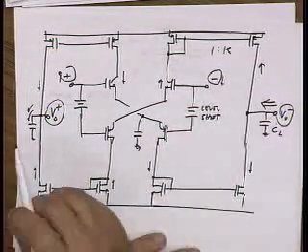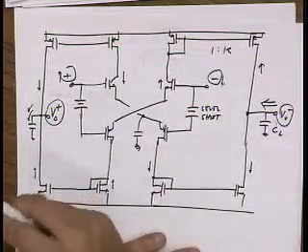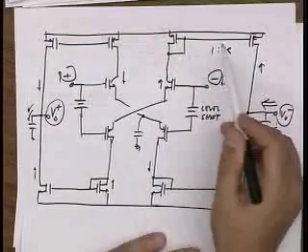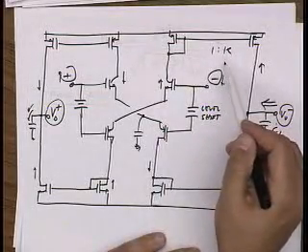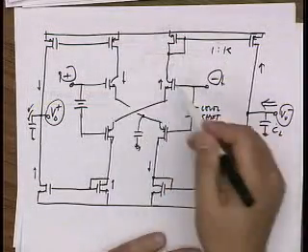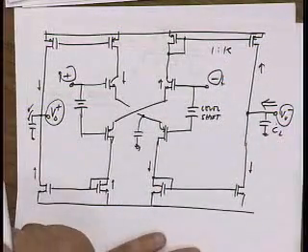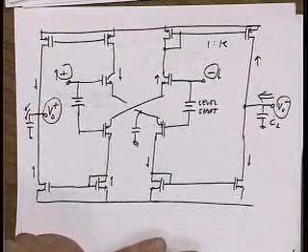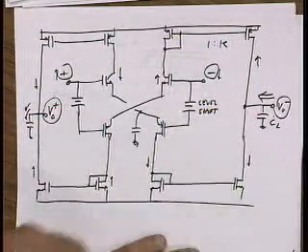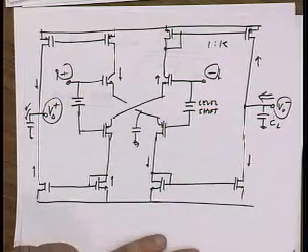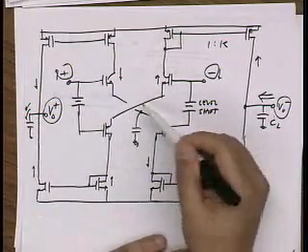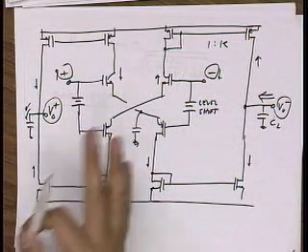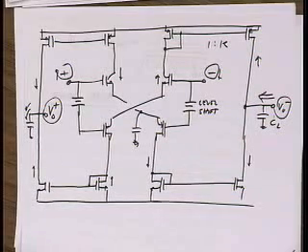It's about Ft over K, right? Ft of the transistor over K. And so because these are PMOS devices, probably this would be my non-dominant pole, Ft over K. But if I'm not careful, I can easily have the input limiting my performance. In particular, looking at this circuit, can someone say under what conditions the input would completely dominate over the mirror? If you're not careful. Let's say you're given this schematic and you've got to lay it out.